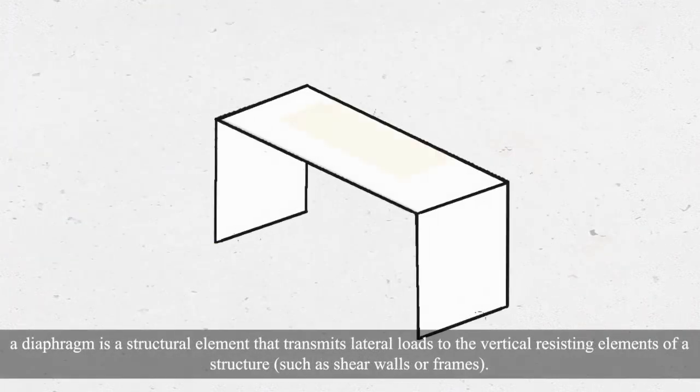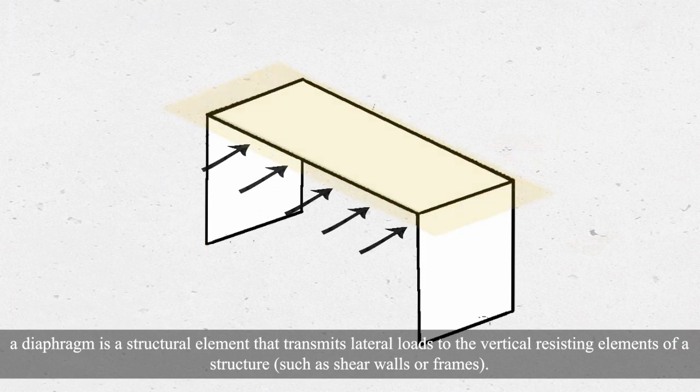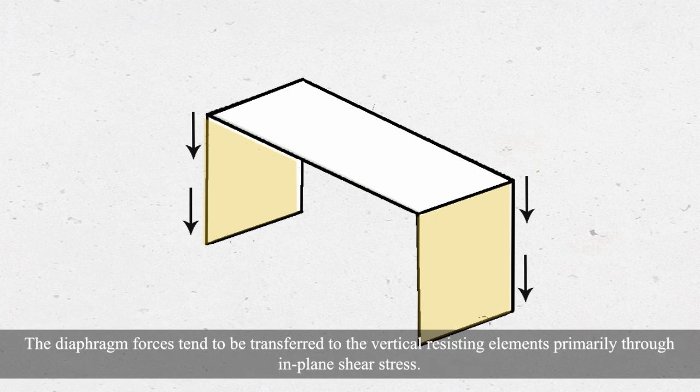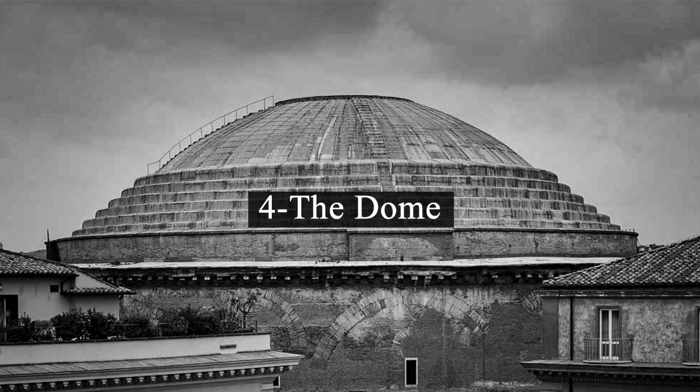A diaphragm is a structural element that transmits lateral loads to the vertical resisting elements of a structure, such as shear walls or frames. The diaphragm forces tend to be transferred to the vertical resisting elements primarily through in-plane shear stress. The fourth element is the dome.